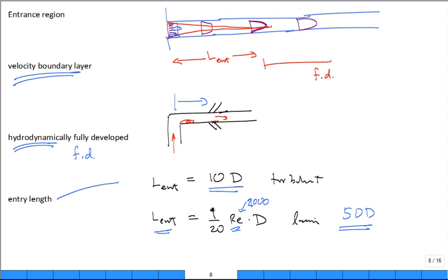A lot of times also in pipes and flows, if they have a bend or entrance region and they're trying to do some ultrasonic flow measurements, they specify how far you have to have where it's straight before you put the instrument in there. Some meters. And guess what? If you go out there and practice, you'll find that the company that installed that meter hired that tech.